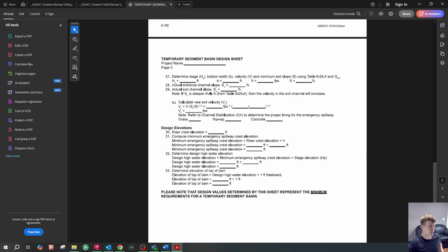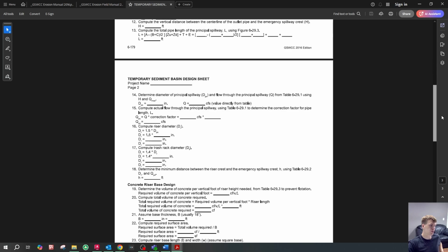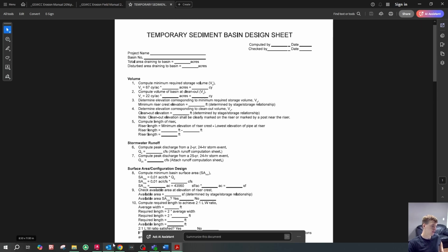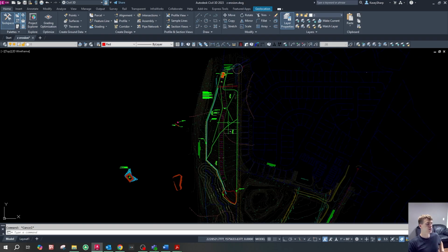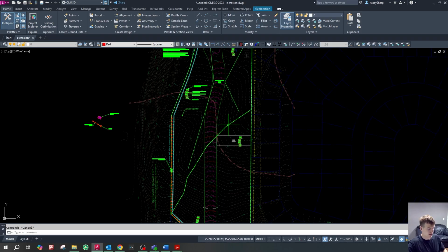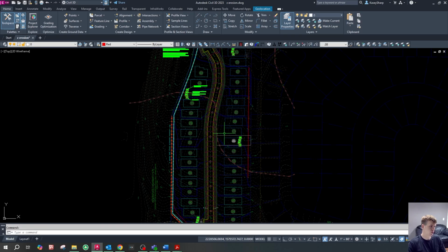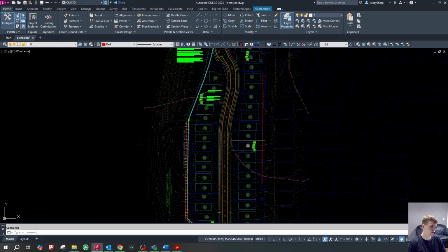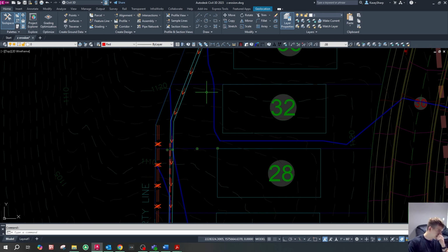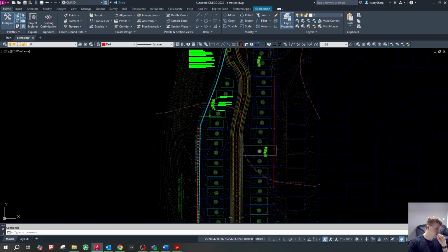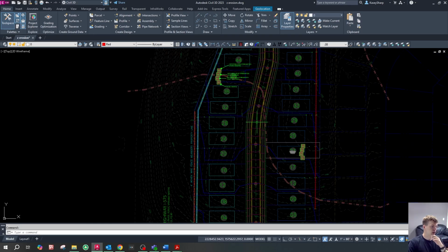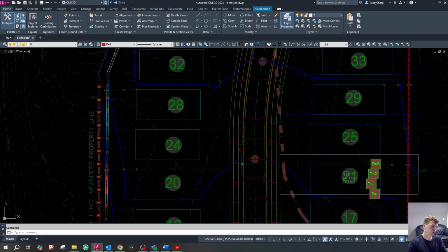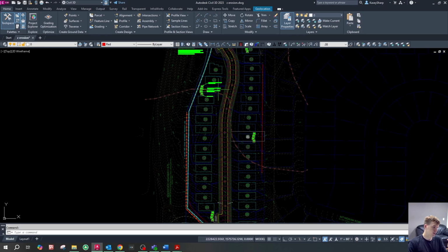So this is basically why we're always going to try and split a site up in order to make it 2 SD4s versus 1 SD3. So this site being 7 acres, that might be possible. So we're just going to look at the site here and see if that's doable. One thing that is pretty typical is we can't locate our sediment traps somewhere where they're going to have to grade out a road or pad or grade out homes. So here it's kind of a cram site, so it's pretty hard.